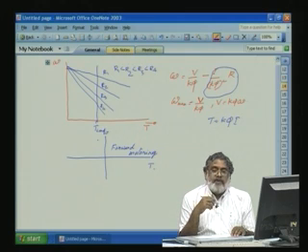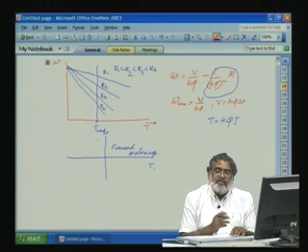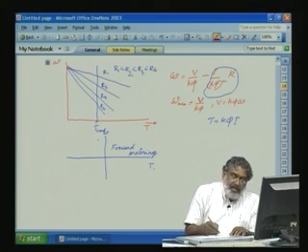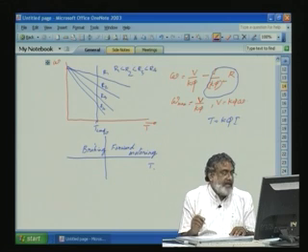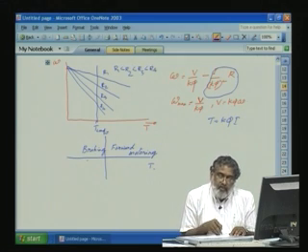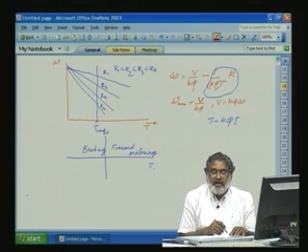For reducing the speed, motor is running, we have to take back the kinetic energy from the system and supply back to the source. That means we should apply reverse torque with the same speed. That is called braking. Torque will be negative, speed will be in the same direction. This can be also called forward braking. Then what will happen to power?